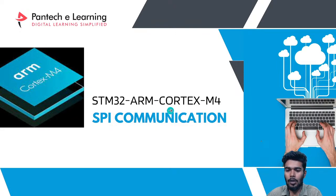Okay, guys. So we will get into the SPI communication. What is SPI? It is a serial peripheral interface. Like I2C, it also can connect multiple slaves, but we can use only one master. So SPI is a single master and multiple slave concept. When you compare with I2C, I2C is a multiple master and multiple slave concept.